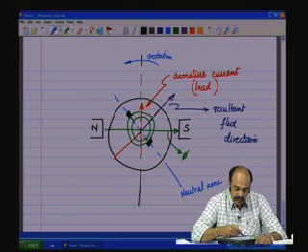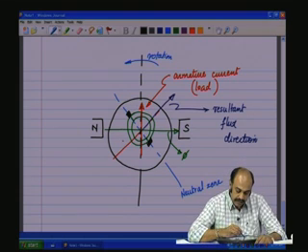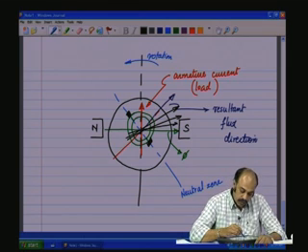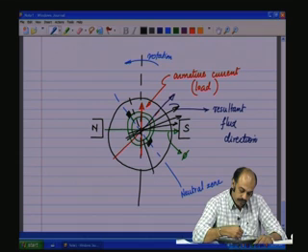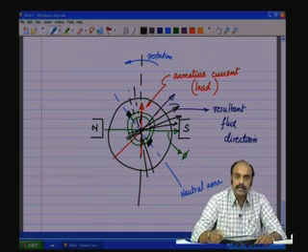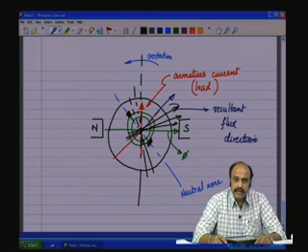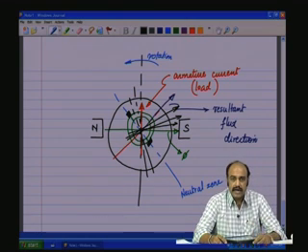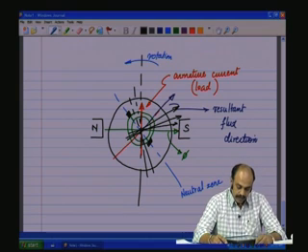So, if this amplitude keeps varying, then the resultant could be in any direction depending upon the amount of load current. So, orthogonal to that only will be the neutral zone. So, we see that the neutral zone has a much higher band of angle in which it can exist at various load currents, and therefore, the brushes cannot be dynamically positioned as the load current changes.